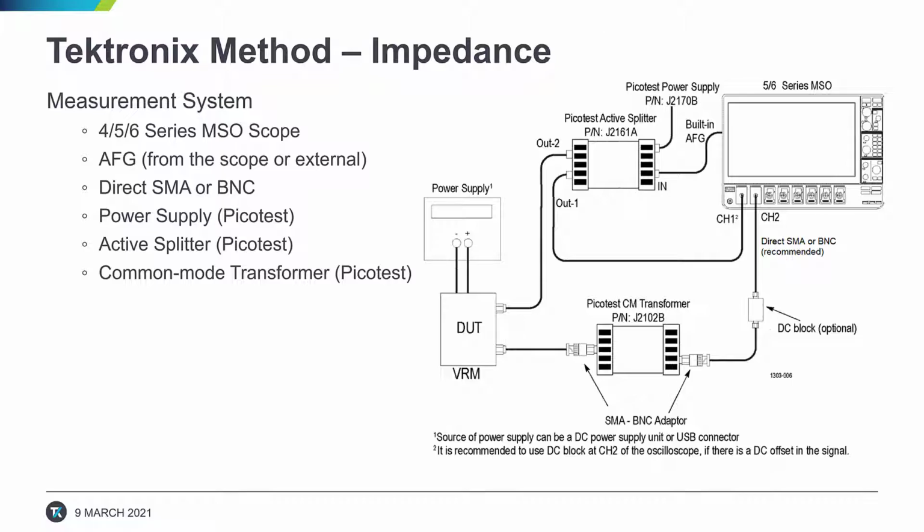And then finally, from a connection standpoint back on the scope side, we can use a couple of different options. The first would be using the bare BNC connections back to the scope channels, or through an SMA connection with an appropriate adapter there. And that can be done using the same 50 ohm or high Z kind of termination schemes that any scope can offer. In this case, especially on the 50 ohm termination side, we generally recommend a DC block to protect the front end of the scope from high voltage type of situations.